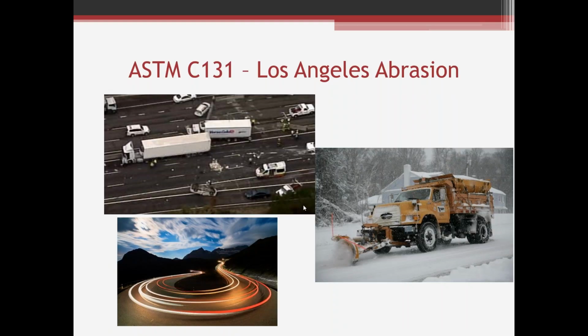it needs to withstand a certain amount of abrasion, whether it's vehicles coming around a corner like this, kind of a steep corner, whether there's accidents that happen, up here in the Northeast, obviously, hopefully not so much anymore. We're getting out of that season, but plow trucks, those plow blades, obviously they're creating a lot of abrasion on the roadways. And the LA abrasion test is not just unique to concrete. We also do it for asphalt as well, for obvious reasons.